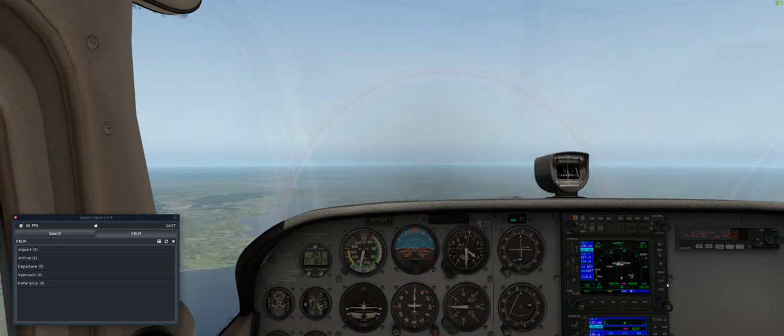Alright, so now we're back on course. What else? I set the VOR to that Atlantic City VOR a long time ago, but we didn't have a signal. Now we do. We're 5.8 miles away from VOR ACY, and we're on radial 140.